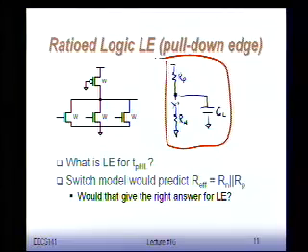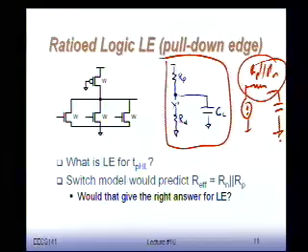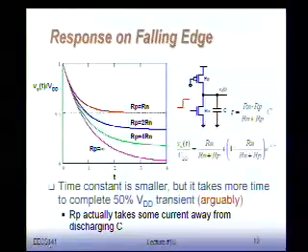Right? If I look at this equivalent logic network, this looks like a voltage source with a step, and then you have RP parallel RN, and you have a capacitor. Okay? So your driving strength is RP parallel RN. What this says is that if you take any large RP or some resistance RP and you put it in parallel with a resistance RN, the combined value is always going to be smaller than RN, which says this will be a fast gate. It actually reduces the resistance. That's cool.